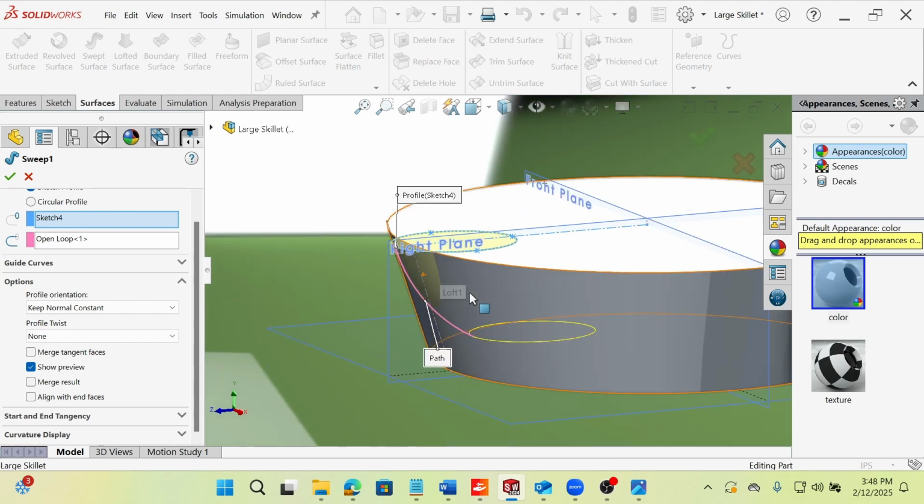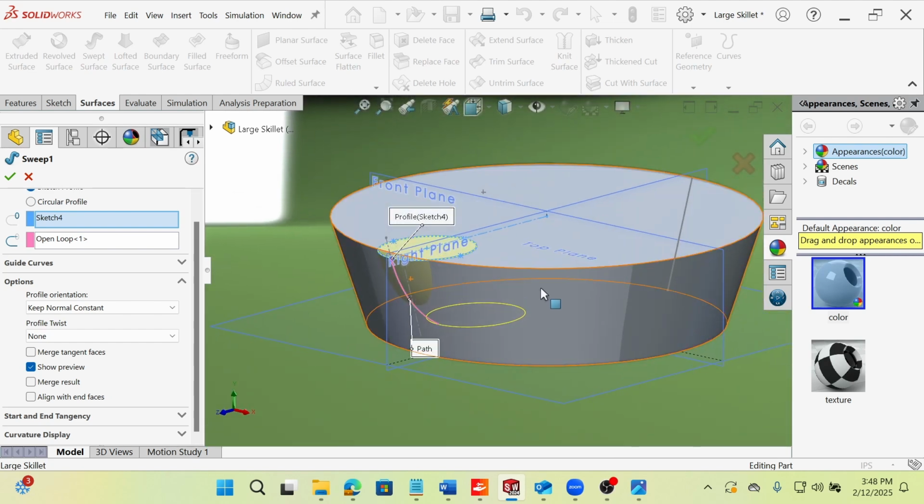So that's another reason to keep everything, especially if you have a symmetric design, aligned with those planes so that you can easily find a sketch plane to sketch on. So almost all my planes you'll see me sketching on here are the top plane, the right plane, and the front plane. Just makes it so much simpler than having to create planes based on offset geometry.